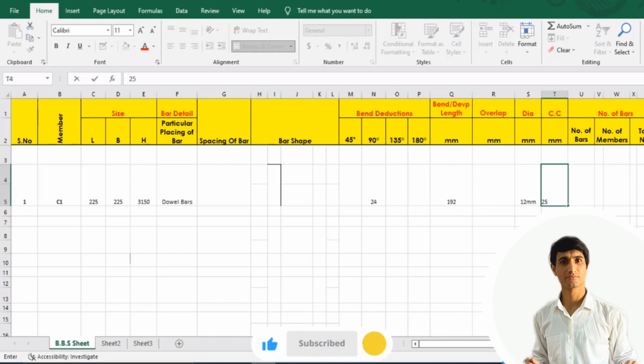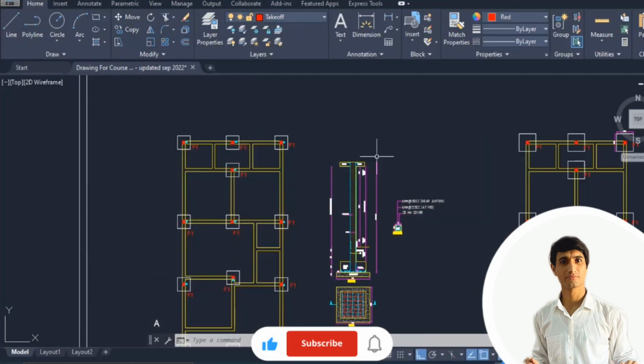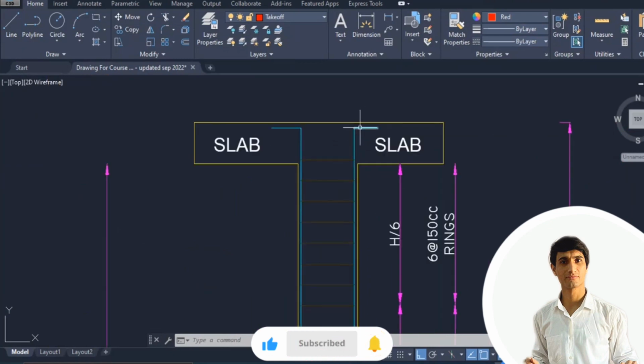But remember one thing, while finding the length of this bar, we will deduct the concrete cover of the slab from the top. This is very important to understand. Let me show you. This bar is going right up to this position, and this is a slab. We need to deduct the concrete cover from the slab.